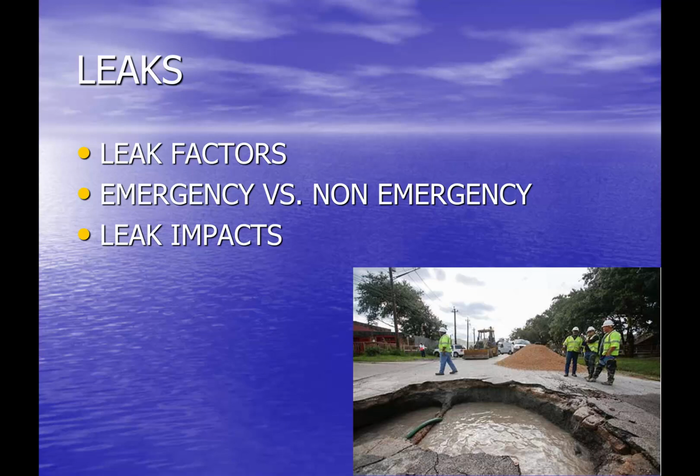The impacts of leaks, the big issue aside from the significant loss of water, is the potential for damage to property and personal injury, especially in a street where you can impact traffic and can have significant injury if a car gets in there. You have the potential for contamination of the system anytime you have a leak. Further cave-ins that exacerbate the area of the damage. And of course the cost.